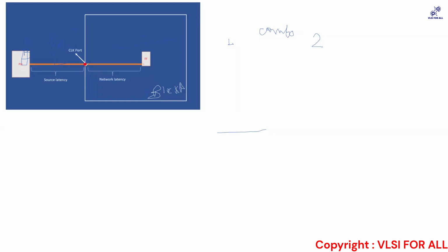Now, guys, you have to do an STA even at the pre-CTS stage, right? Even at your synthesis stage, you are performing STA. Even at your floorplan stage and placement stage, you are performing STA, before CTS is done. We will go into the complete PNR flow later.